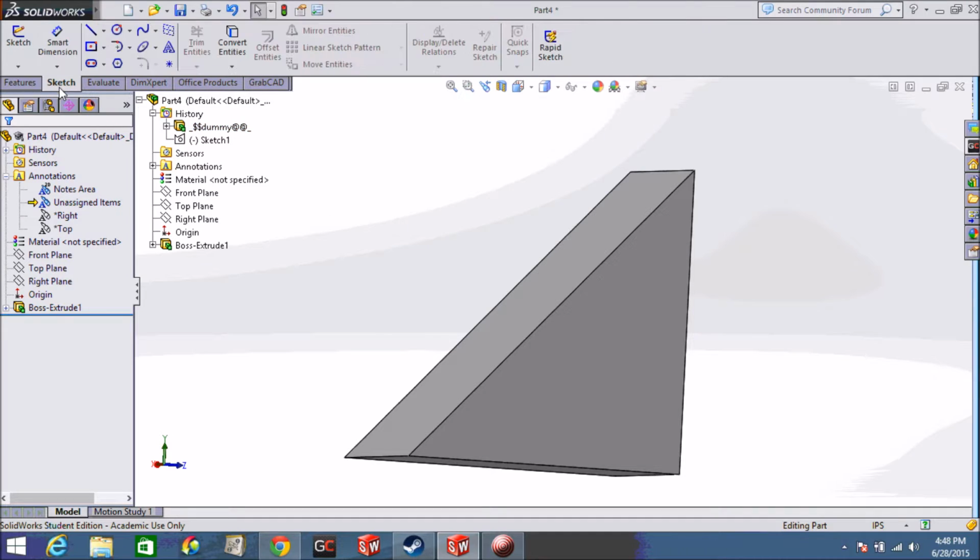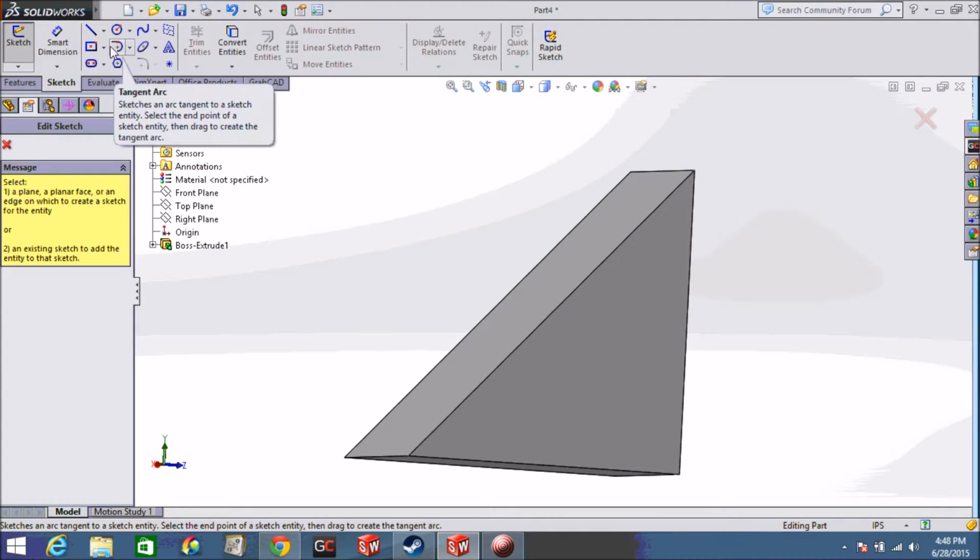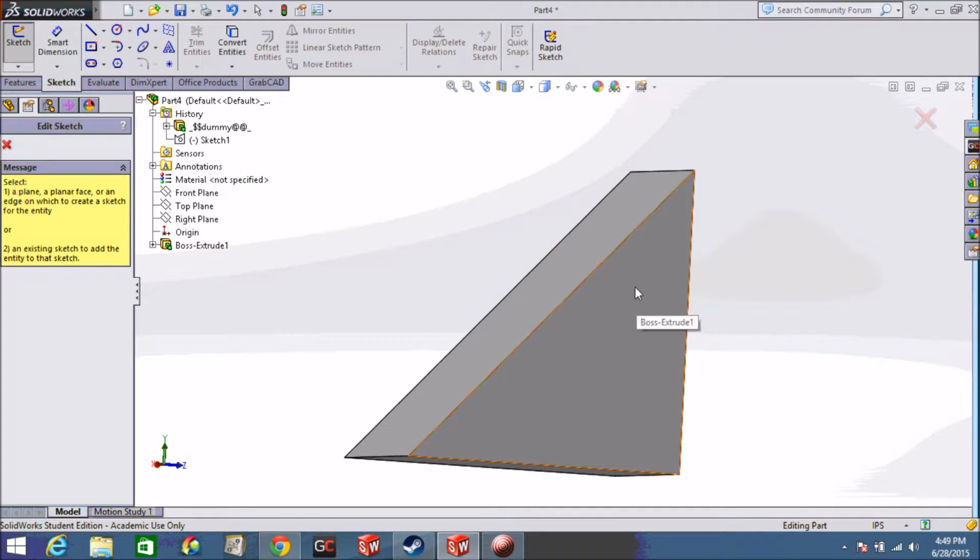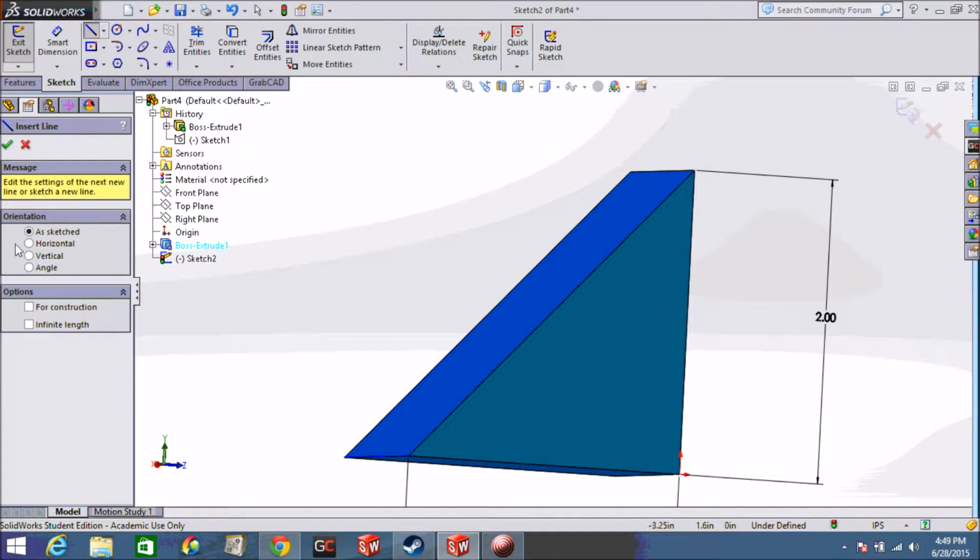So what we're going to do that is we're going to start out with, once again, a sketch. Now, here when I click the sketch button, I need to select a plane to draw the sketch on. And now that I'm not working anymore in an empty space, I have to choose a plane on an object. So I'm just going to choose the side plane here. Well, this is not completely arbitrary, but anyway.